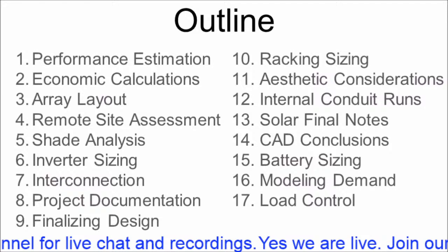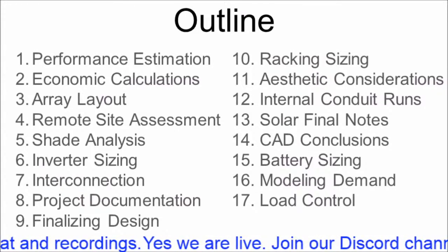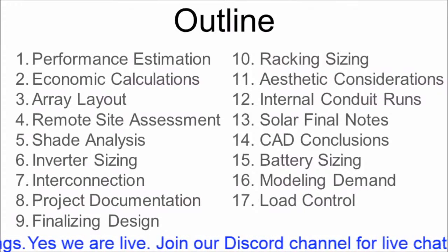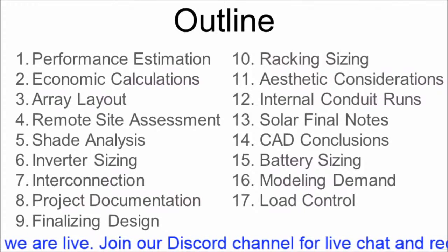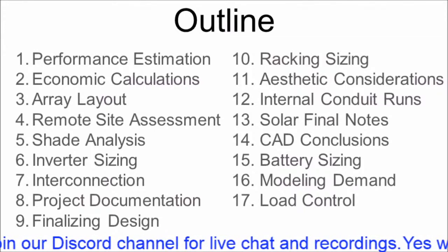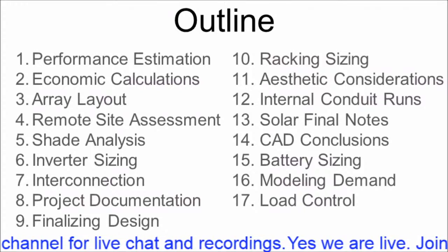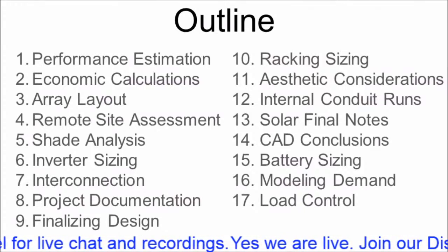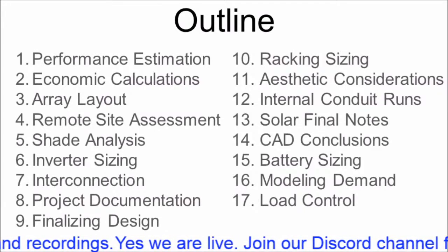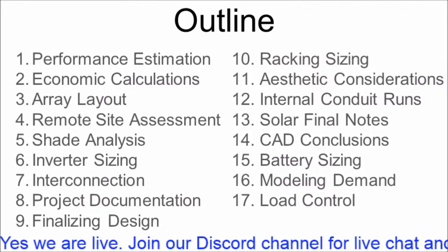Our program outline today is pretty robust, so we're going to get started right away. In this program, we'll be covering everything you need to know to evaluate the preliminary design process of a rooftop solar array. So we'll be covering performance estimation, economic calculations, array layouts, site assessment techniques, shade analysis, sizing the inverter to get the relationship right between the array and the output capacity, different interconnection strategies based on service